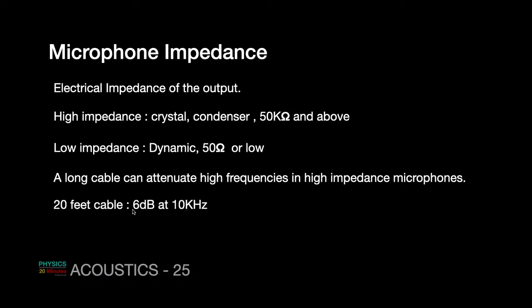For example, if you have a 20 feet cable, then at 10 kilohertz, it can attenuate the signal by 6 dB. So long cables should be avoided. However, practically it is not always possible. For example, if there's a stage presentation, then the long cables do come in the picture. However, present day microphone technology is quickly moving towards wireless, Bluetooth and other techniques that we are obviously not covering because the course deals with the basic structure of sounds.